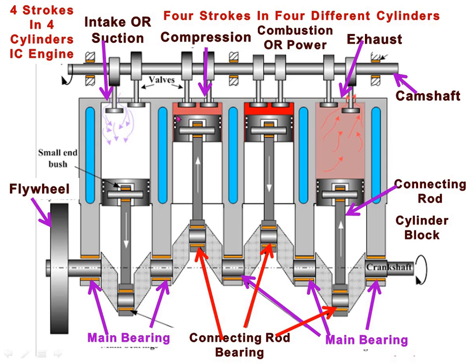At the end of the compression stroke, the piston reaches top dead center, and the air inside the cylinder is compressed in the clearance volume of the cylinder. Then at that time, the fuel is injected through the injector, and this compressed air is very hot, having high temperature.